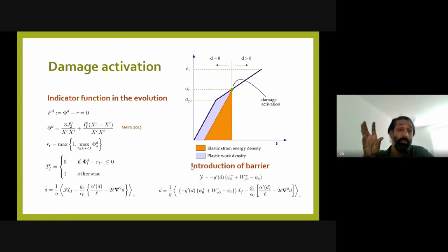But here we want to propose a damage activation function, which has also been observed experimentally in epoxy materials. This damage activation function takes into account both the invariants of the stress. So it is basically an invariant based damage activation. We basically get a multi stress criterion, so that it is not a constant failure strain or tensile failure strain that we are giving. It is going to be a complete surface. To model this, we have the loading function FD, and this is the damage activation surface. When our loading reaches that surface, the damage is activated.